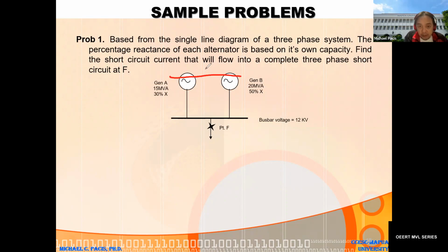Since these are independent sources, you need to neutralize the sources by having Vs equal to 0, by short-circuiting the source, and then represent it by the model we computed, j0.7 and j0.875, by changing the bases using the change of base formula, so modeling the percentage reactances.